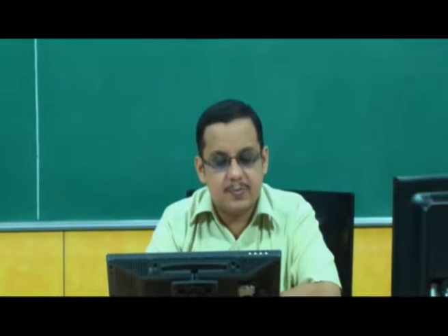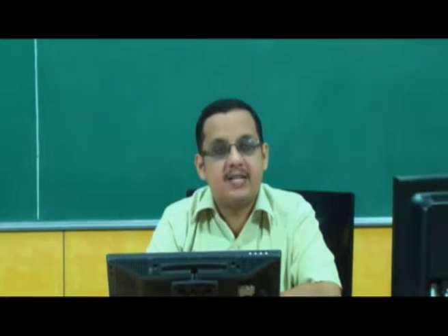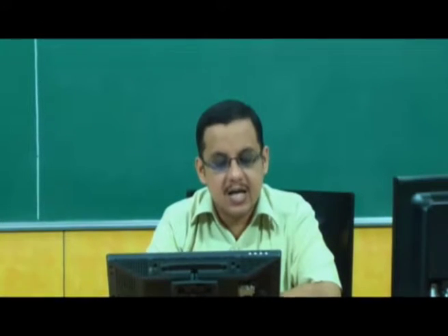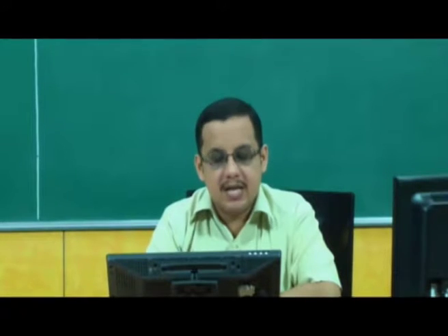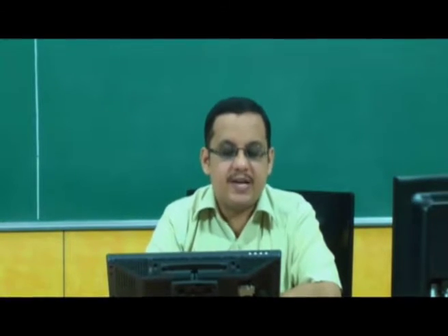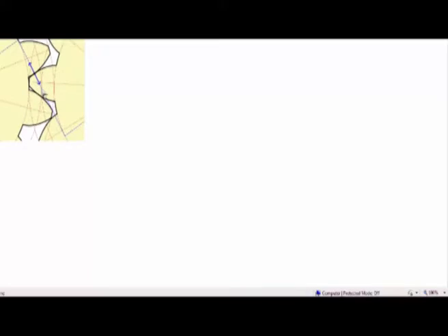In other words, the pitch point, exactly where I have held my cursor, is going to be fixed during the course of engagement. And the pitch point being fixed essentially tells me, through the fundamental law of gearing, that the velocity ratio is constant during the process of engagement, and therefore these tooth profiles are conjugate.